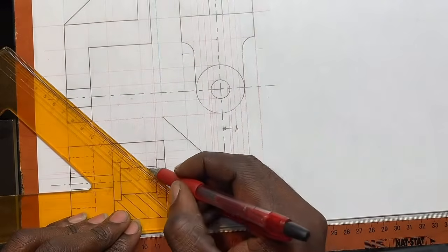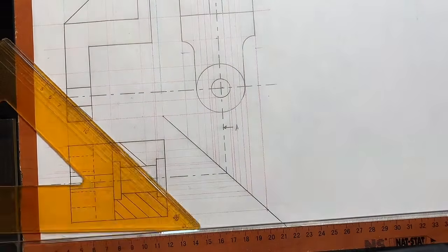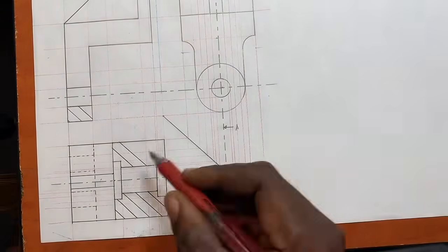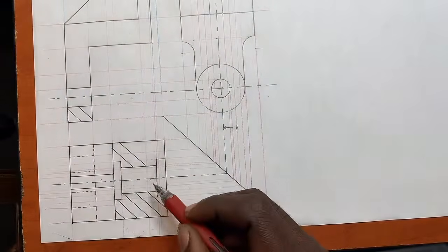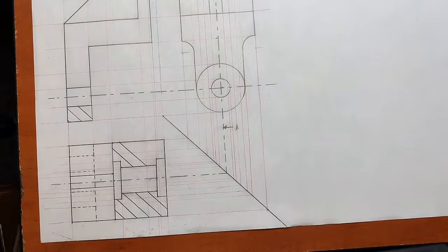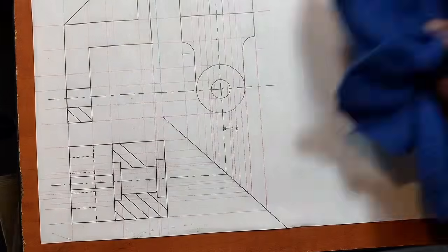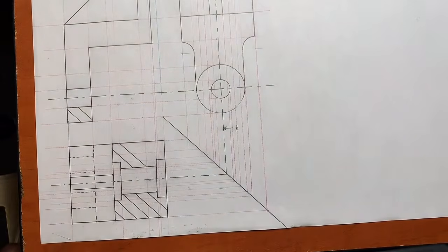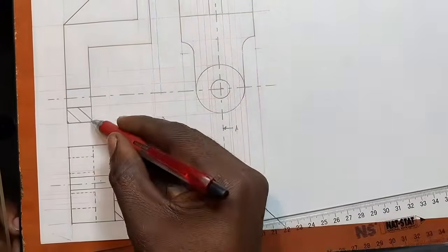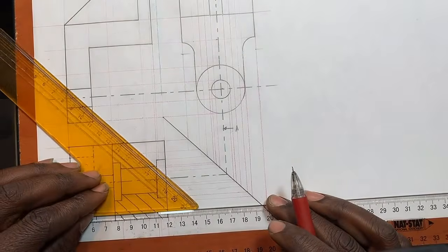Remember, your hatching always starts from a solid line to a solid line. When you section, from a solid line to a solid line, you understand? So you don't say, assuming there was a solid line along this hatch, I should get rid of that solid line. We don't section on top of a solid line. We do not section on top of a chain line or a hidden line. You understand? Whether that hidden line is supposed to disappear or is supposed to change dark. So we section from a solid to solid. But we do section on top of what? Of a center line.